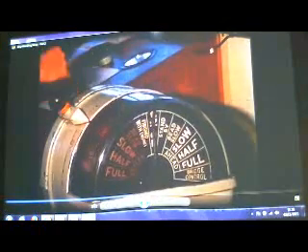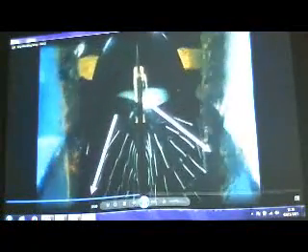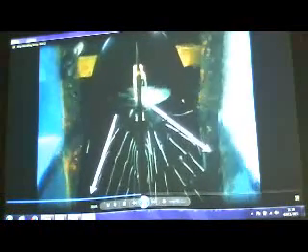Now consider a different situation. When the propeller is turning astern, the water generally enters the propeller disc at a uniform velocity and direction, so there is no transverse force generated by the propeller alone. However, the propeller still produces a helical discharge, and when this strikes the after body of the hull, viewed here from below, it induces a down and inward component of flow on the port side, and an up and outward component on the starboard side. This causes a higher pressure on the starboard quarter than on the port quarter, which pushes the stern to port.